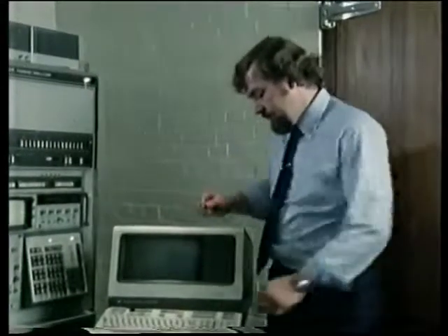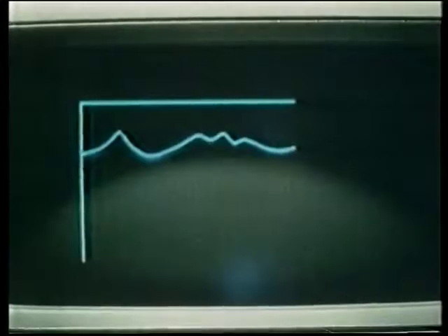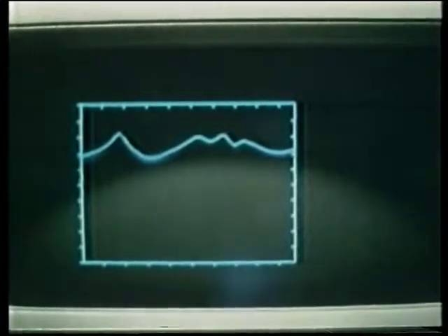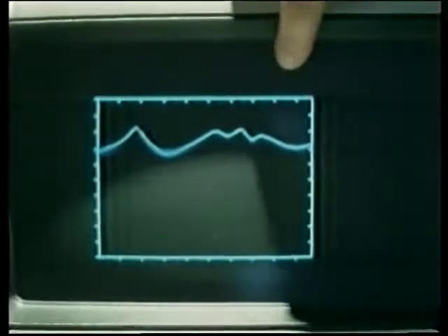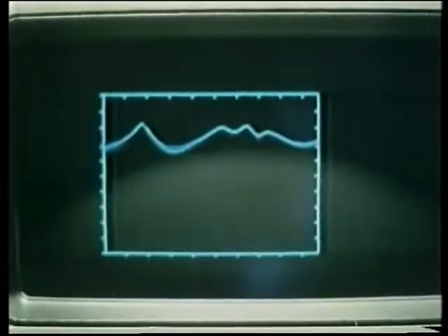Well, Mr. Cook's shown us how a systems approach to loudspeaker design helps us to obtain a satisfactory frequency response. But there's another point that must be considered by both amplifier manufacturers and loudspeaker manufacturers, and that is that the impedance of a speaker varies with frequency. I've got a typical plot here. In this case, we've plotted the logarithm of the modulus of impedance against log frequency. You can see it's certainly not constant with frequency. You'll see how we can cope with this in the amplifier case study.